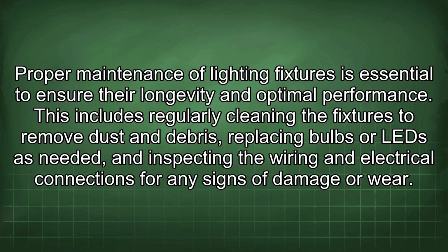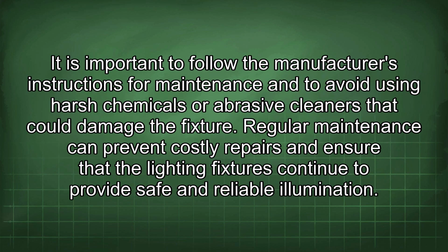Proper maintenance of lighting fixtures is essential to ensure their longevity and optimal performance. This includes regularly cleaning the fixtures to remove dust and debris, replacing bulbs or LED as needed, and inspecting the wiring and electrical connections for any signs of damage or wear. It is important to follow the manufacturer's instructions for maintenance and to avoid using harsh chemicals or abrasive cleaners that could damage the fixture. Regular maintenance can prevent costly repairs and ensure that the lighting fixtures continue to provide safe